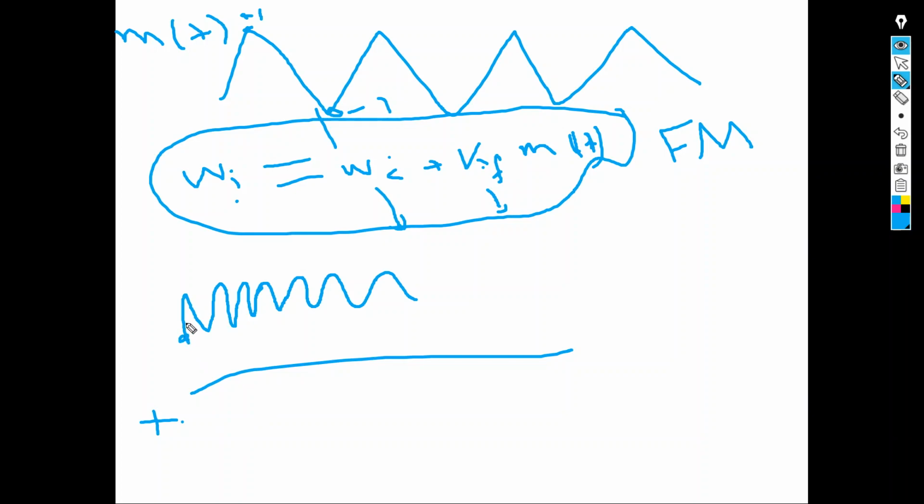As you can see, the frequency is increasing little by little, so the receiver knows that the signal is going up with a certain slope. This information is shared ahead of time, and then it goes down, goes up, and the receiver can detect the signal back. It won't be exactly perfect, but close to what you transmitted.